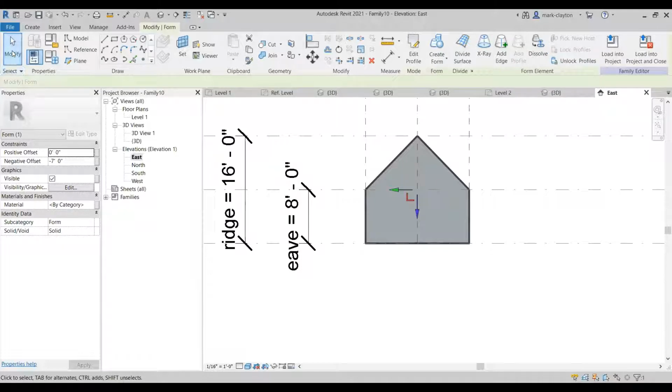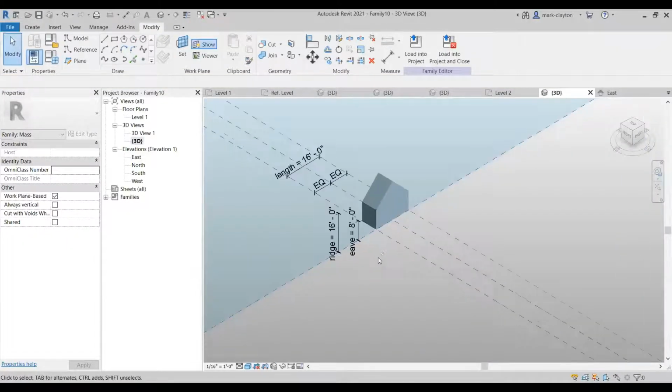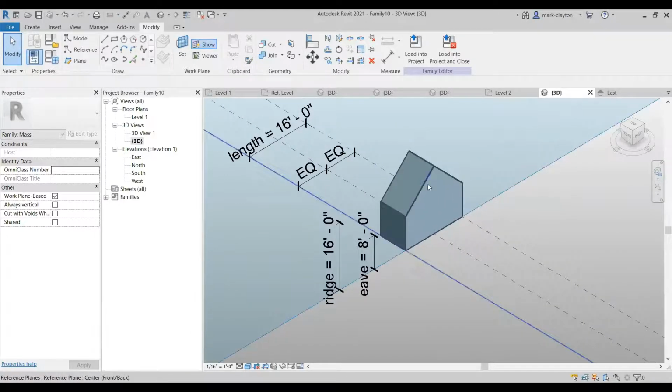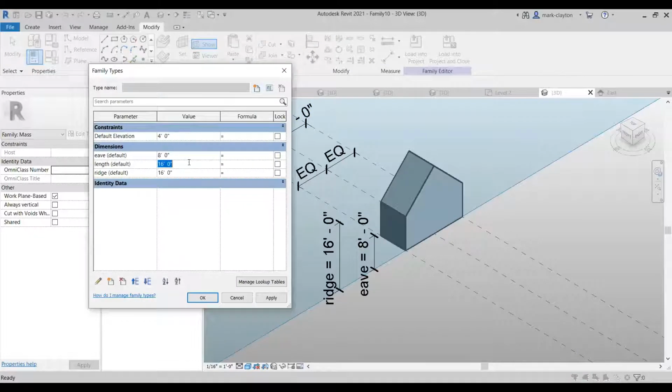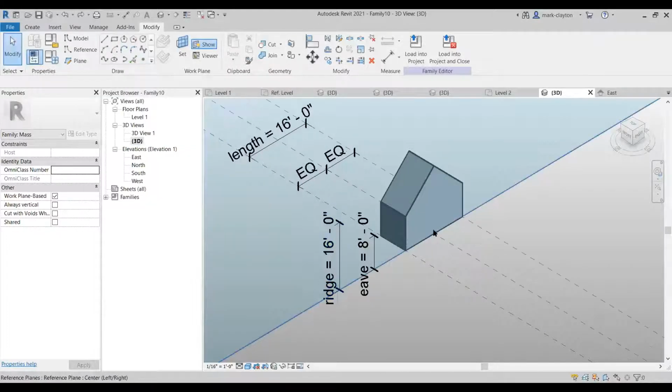I'll lock the profiles here. So, now I've got this little shape, and I test it. This is called flexing the model. I flex the model to see if it works. No, doesn't work. So let's cancel, undo, and go back. Yeah, I need to lock those edges.